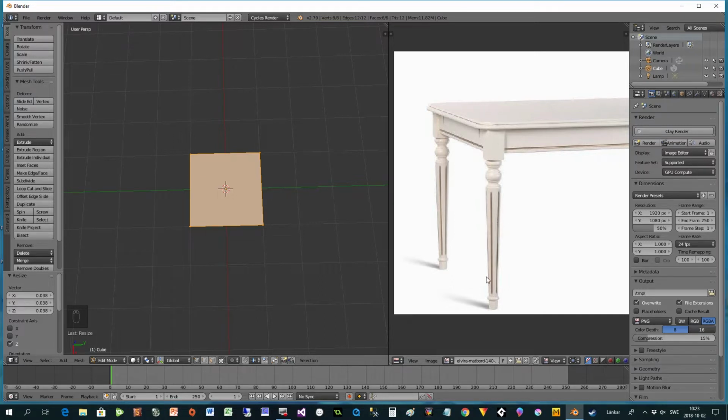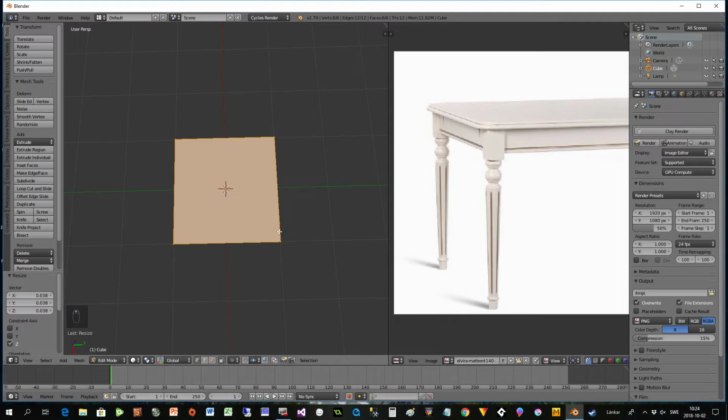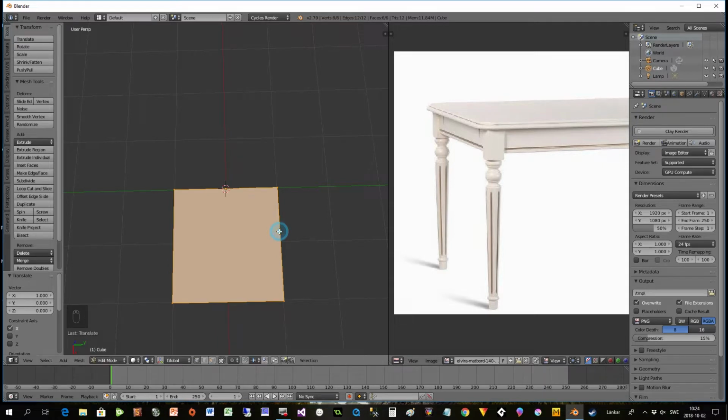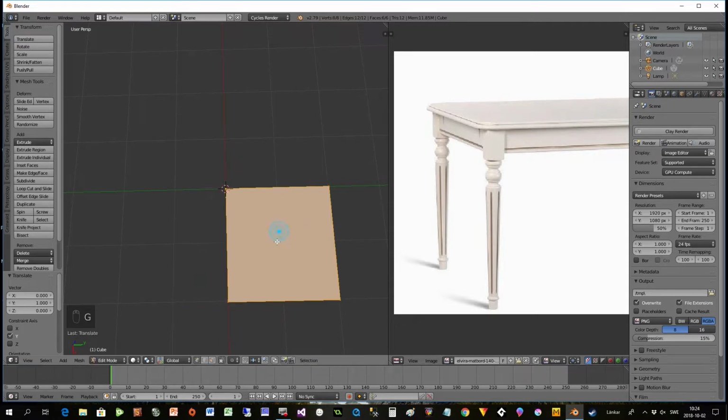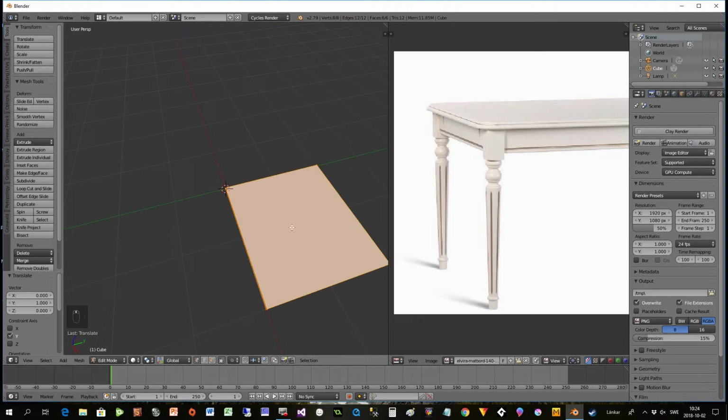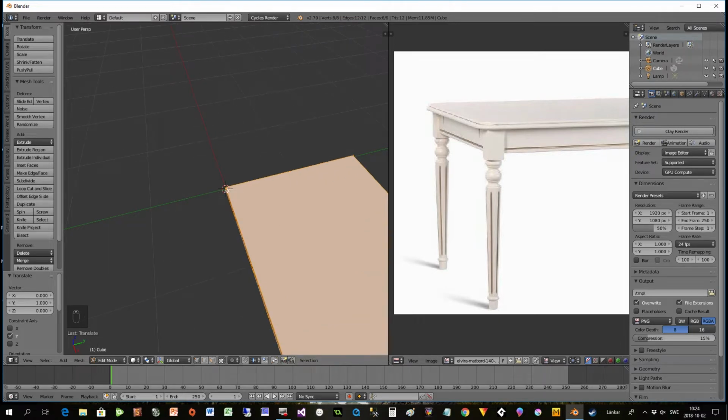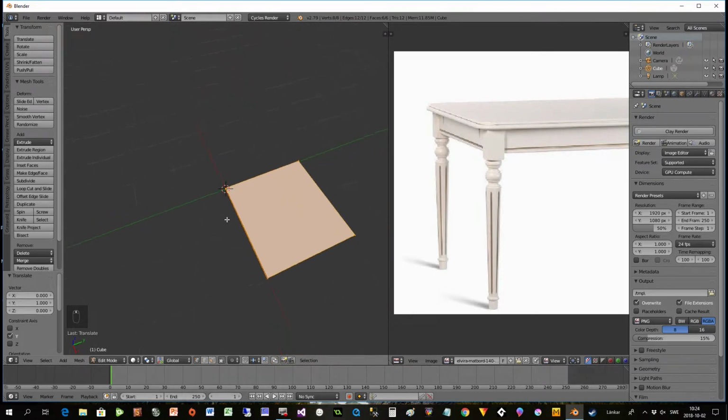Just do one leg and then the other ones will automatically be copied if I use a mirror modifier. So I press G for move or grab X1, GX1, and then GY1, and then I moved everything, but I have my start point, as you can see, in the corner here.